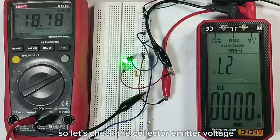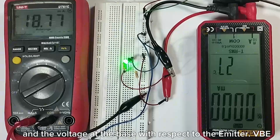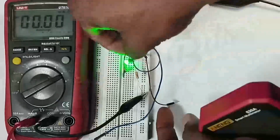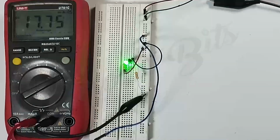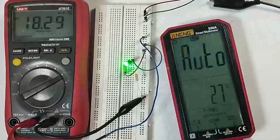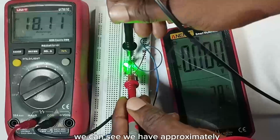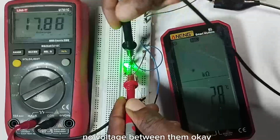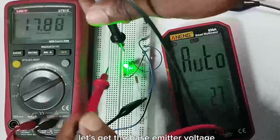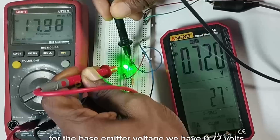So let's check the collector-emitter voltage and the voltage at the base with respect to the emitter, VBE. Okay, so for our collector and emitter, we can see we have approximately no voltage between them. So we are actually in saturation. Let's get the base-emitter voltage. For the base-emitter voltage, we have 0.72 volts.